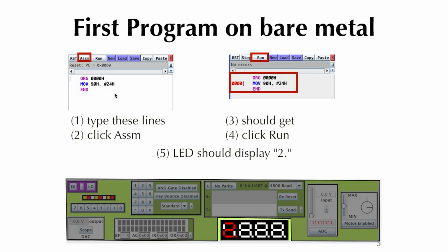So this Edsim assembler will use syntax highlighting to indicate what is an instruction versus what is called a directive. A directive is basically directions for the assembler. It does not translate into an actual instruction for the target machine, whereas if it's a blue type of thing, then yes, that corresponds to an actual machine instruction. Now, how many bytes does it turn into? Well, it depends. We'll see that. And in fact, I include a data sheet so that you can take a look and even hand assemble if necessary. You should do that sometime just for fun.